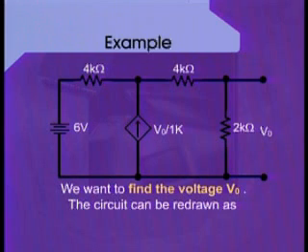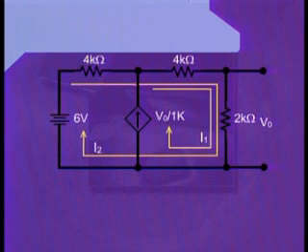As our usual practice, we have to declare the currents for various meshes, and also we have to declare the area of the super mesh so that we can simplify our circuit analysis. Apparently, this circuit consists of two basic meshes, and we declare these two meshes with some numbers 1 and 2. Also, we declare the current I1 flowing through the mesh number 1. And also, we have drawn this current in the clockwise direction.